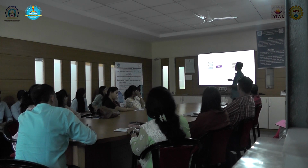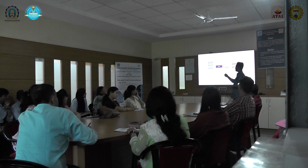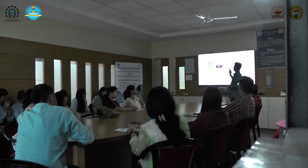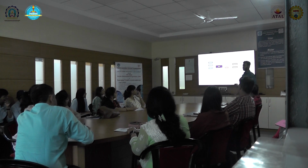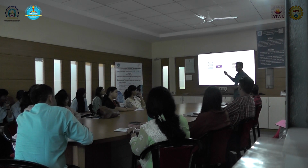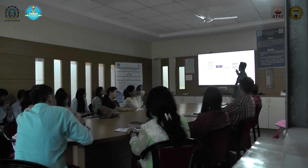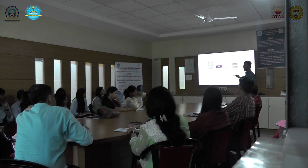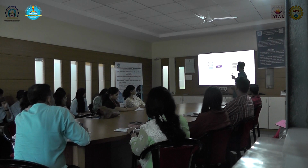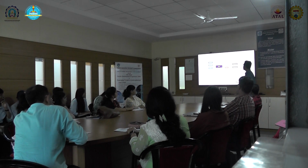Then after we run this, we will get our status, like I explained earlier, proven or false, right? If the assertion gets proven, we can be sure that all the legal scenarios are exercised and the design works. If there are any failure scenarios, we will get a waveform, a failure trace, we can see and debug it, and we can update the design or the assertions based on the traceback or the debugging view.